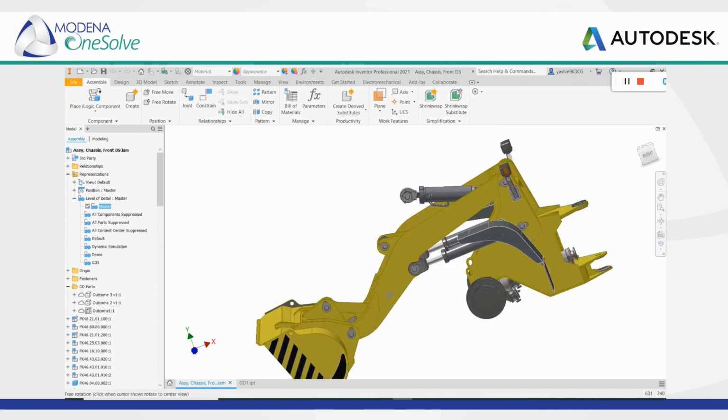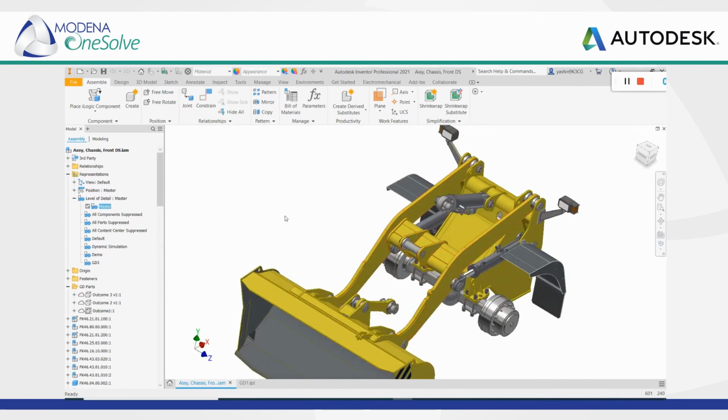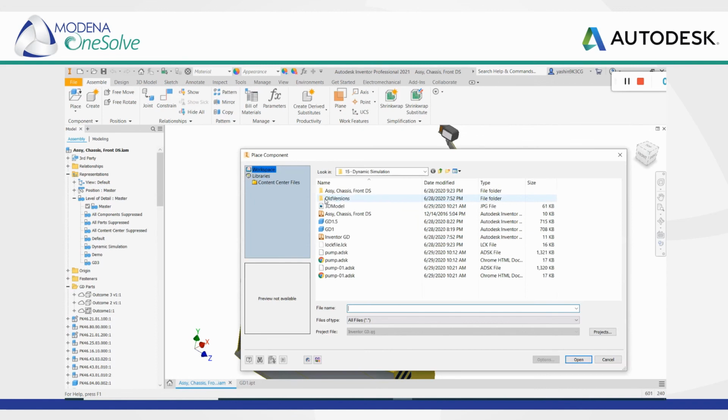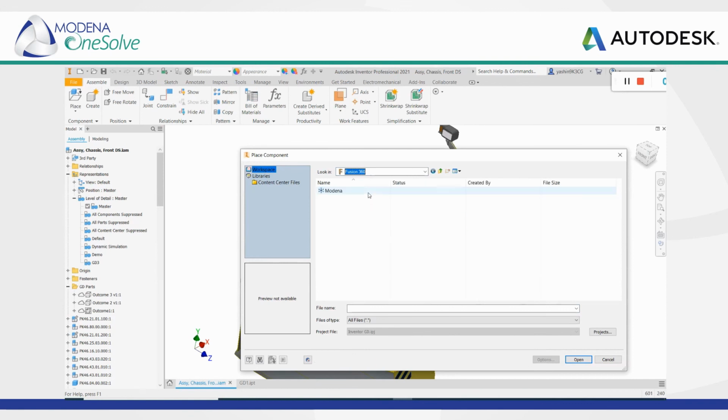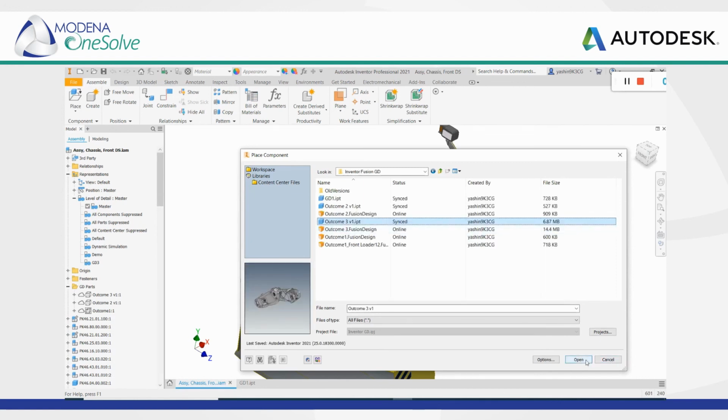So with our main or master assembly open inside of Inventor, we can place that component from our Fusion 360 desktop connector very quickly. So I'm just going to head over here, choose the place component option, and head over to my Fusion 360 cloud location where we stored this information. Open up my Modena Team Hub, and access the project folder where the CAD model, or the generative design outcome, was stored.